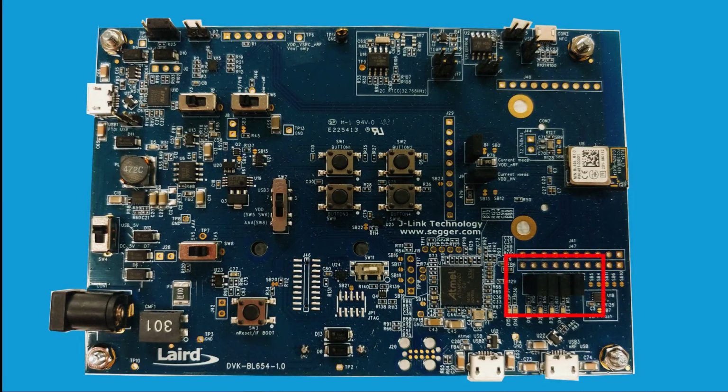Please be aware that if the 4 jumpers on the bottom right of the board are missing, the 4 LEDs will not operate for the demo, which relies on switching the lights on and off. First, we will connect our BL654 to the PC with the included micro USB cable. The power LED illuminates when the board is receiving power. If the power LED does not light up, ensure switch 4 is set to USB as shown earlier in setup.